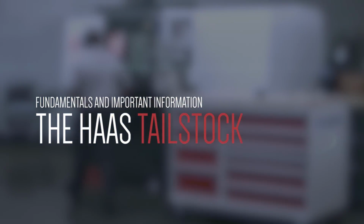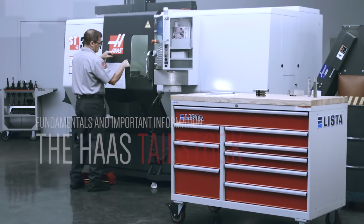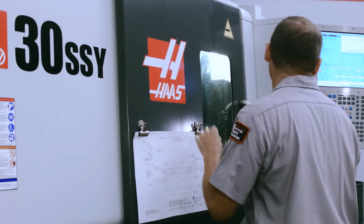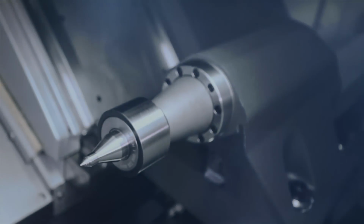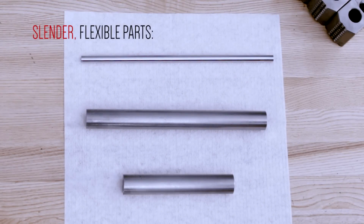Today, we'll discuss fundamentals and important information for using the tailstock on your CNC Turning Center. The tailstock option, available on all Haas lathes, adds versatility to the turning operations you can perform. But what do you need a tailstock for? Slender, flexible parts are probably the most common application where tailstock support is required.